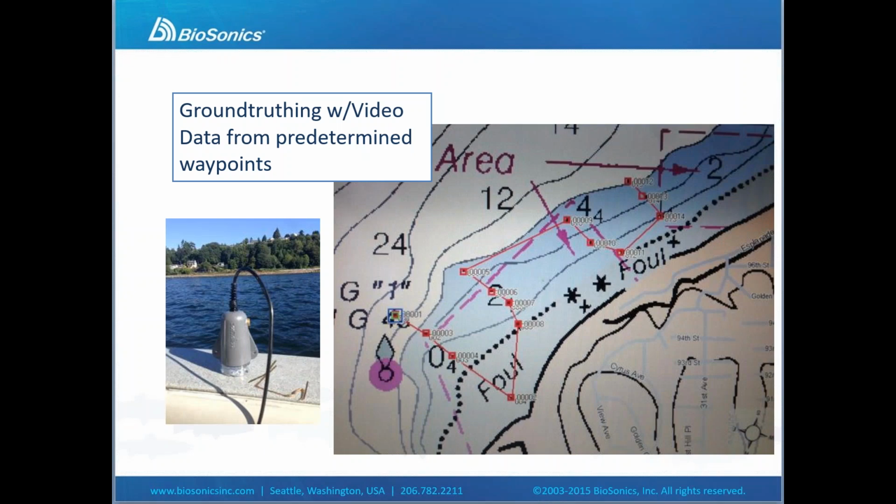If we want to know the substrate type, then we are going to need to take a sample or two from the different areas. The beauty of it is, though, because we've processed, we've made our map, but we have the coordinates, we know where all the points are for type 1, type 2, and type 3, to the type X. So we can go out, take a few sample coordinates, and go do some ground truthing and assign a value to those different types.